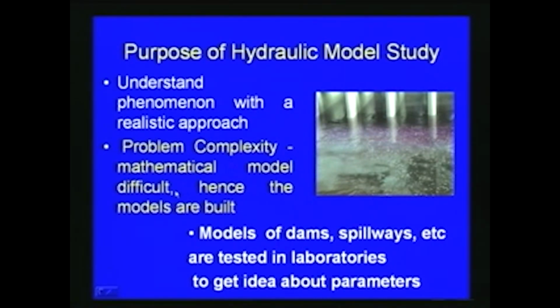The mathematical model is difficult, but if you do the modeling appropriately with respect to scale, we can see how much turbulence is generated, whether the pumps are affected or the system is stable. In some cases where theory cannot directly solve the problem or mathematical modeling is difficult, physical modeling or hydraulic model study helps.